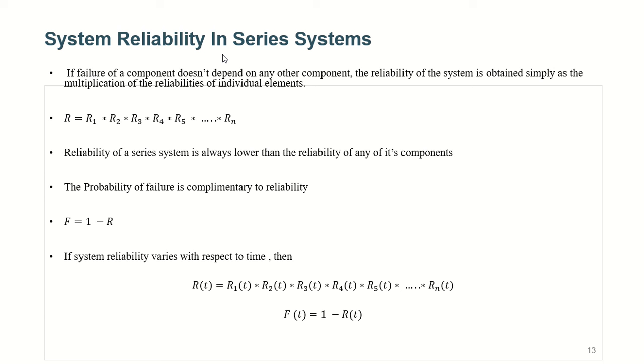It must have so many components, and if we connect all of them in series operation, what will happen? The failure rate will be so high. You would not like to sit in an aircraft that has a high failure rate of its engine, would you? Right? Because it can lead us to catastrophe. So always remember, in series operation we do not take so many elements, because the reliability gets too low, and the probability of failure increases very quickly.